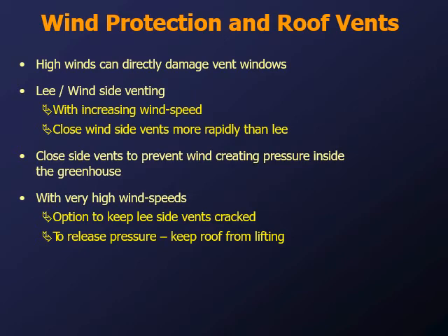So it's important as a grower to not just rely on the computer, but use your head. If you know there's a storm in the forecast, you should already be careful and be monitoring the greenhouse. And if you see dark skies approaching, you're going to manually lock down your vents or limit them to a small percentage so that the glass doesn't lift off and smash.